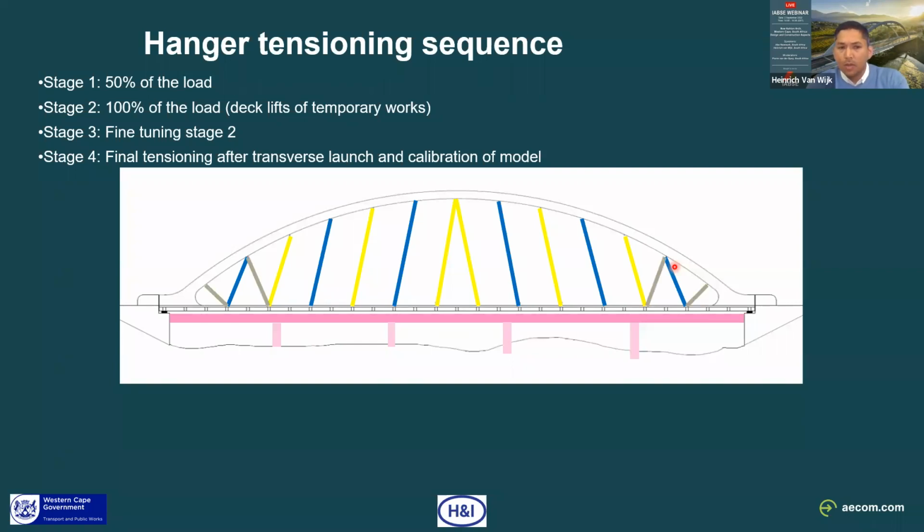Whereas the inward leaning cable, which is the cable in gray here, has the vector orientation pulling inwards, and this cable is almost perpendicular to the arch curvature, and the arch is very stiff when these cables are tensioned, and your result is that you pick up the deck. It has a better effect of pulling up the deck with the inward leaning cables.